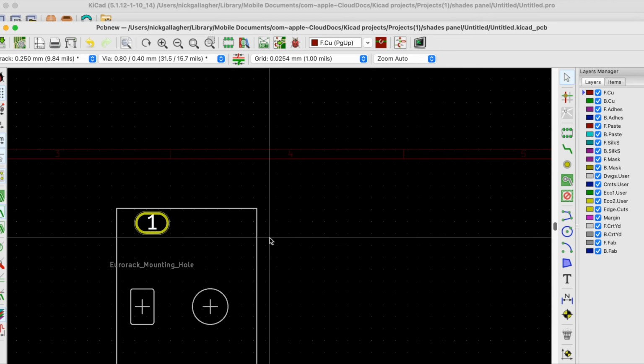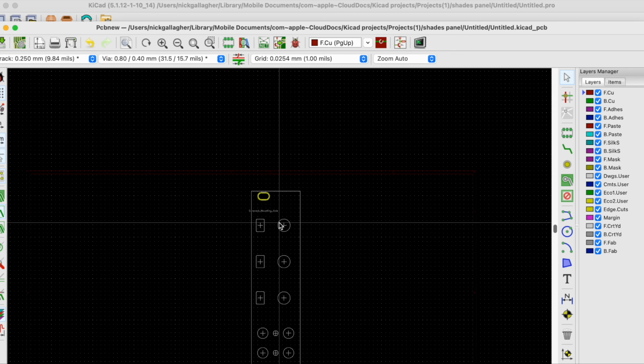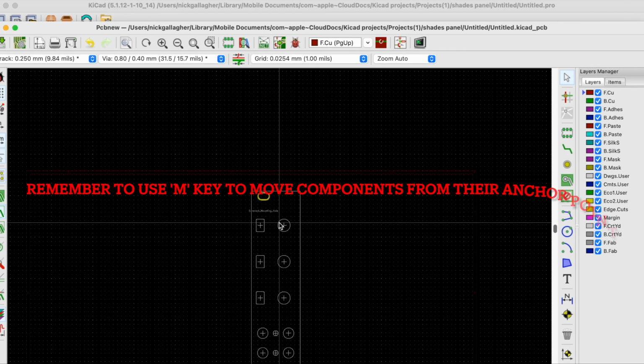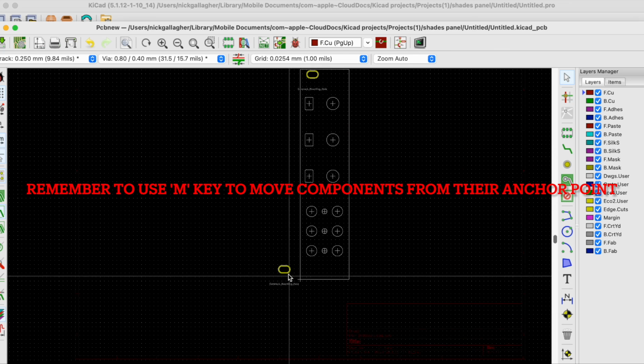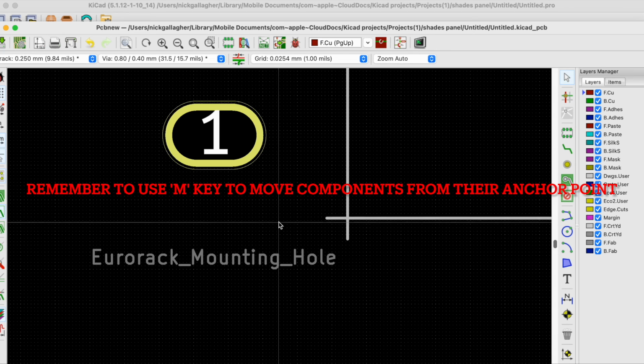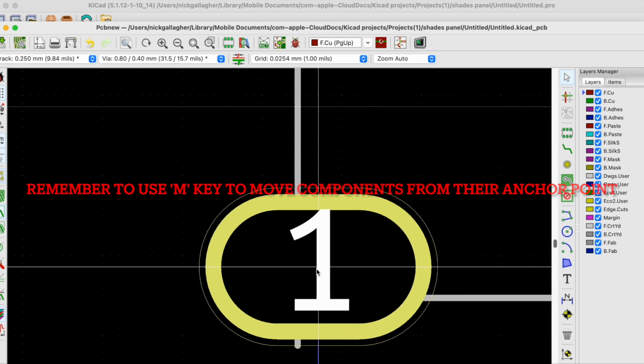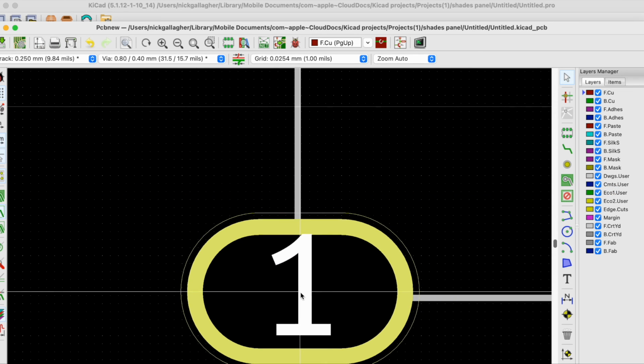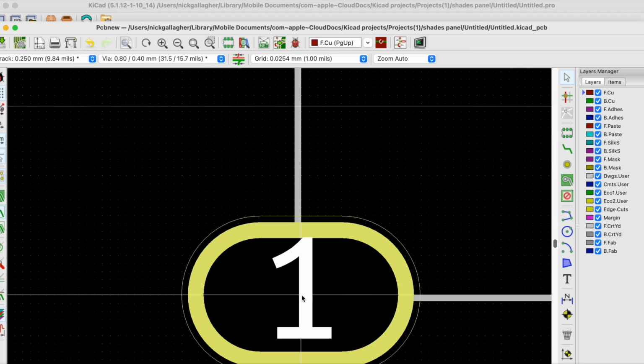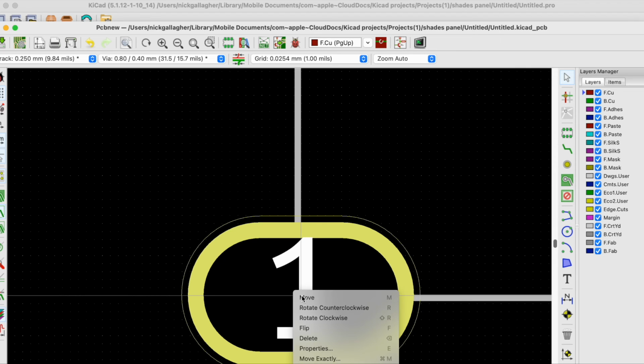And now we're going to repeat that process for the bottom rail mounting hole. The only real difference, since you're still on the left side of the panel, the x-axis is going to be the same, so it's still going to be 7.5 to the right, but this time you're going to want to go up in the y-axis, so you're going to do -3.